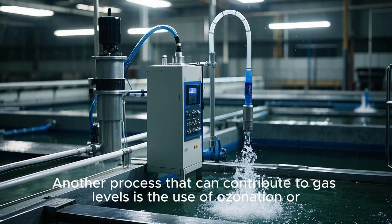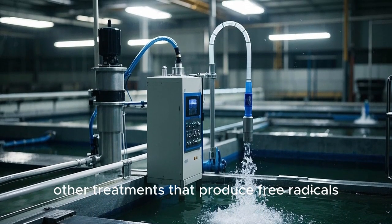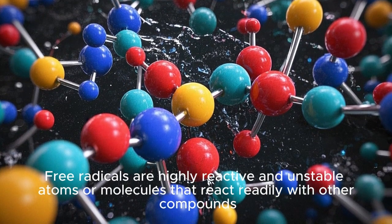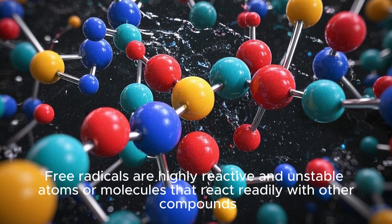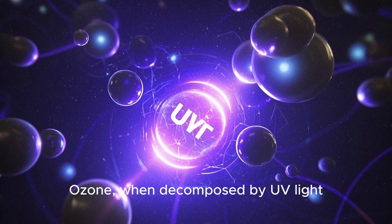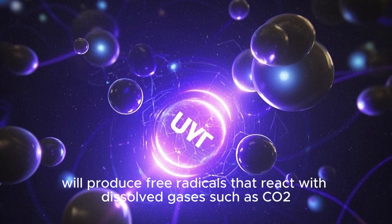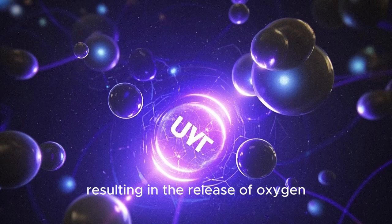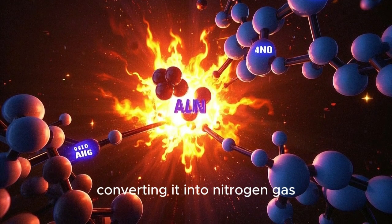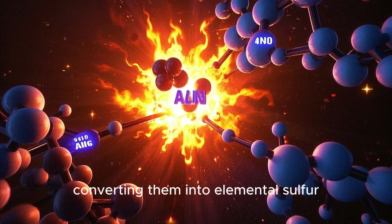Another process that can contribute to gas levels is the use of ozonation or other treatments that produce free radicals. Free radicals are highly reactive and unstable atoms or molecules that react readily with other compounds. Ozone, when decomposed by UV light, will produce free radicals that react with dissolved gases such as CO2, resulting in the release of oxygen. Free radicals can also react with ammonia, converting it into nitrogen gas, or react with sulfides, converting them into elemental sulfur.